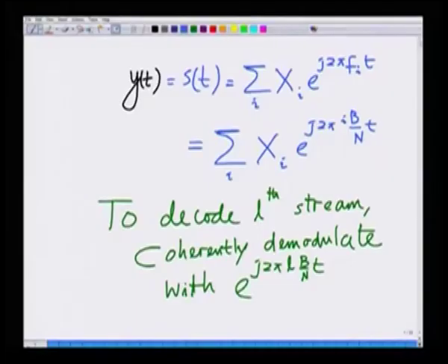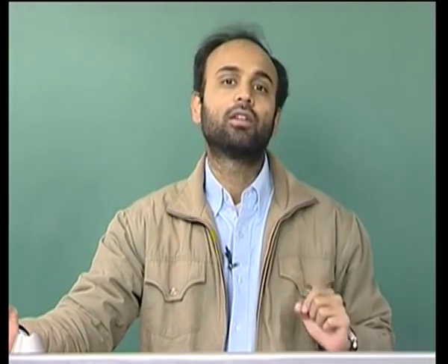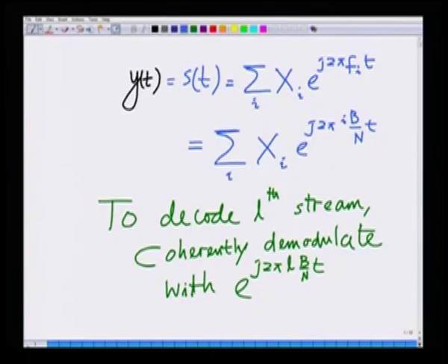In the last lecture, we were discussing multi-carrier modulation. After modulating the transmission symbols on multiple subcarriers and transmitting this composite signal through the communication channel, the data symbol on each subcarrier can be coherently demodulated by employing the subcarrier e^{j2πlBt/NT}. That is, I am demodulating the symbol transmitted on the Lth subcarrier using coherent demodulation with the Lth subcarrier.